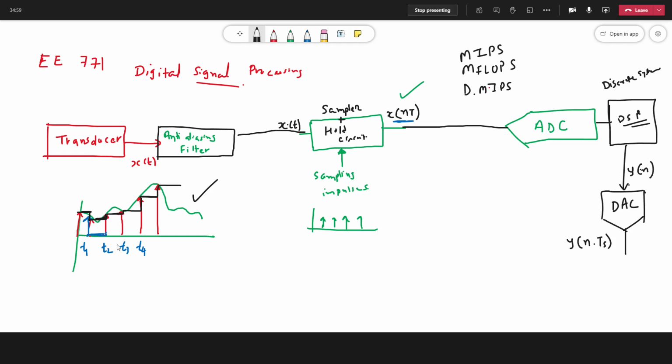So these are the moment when digital to analog converter will change its output suddenly. Now this sudden change in signal actually represents presence of high frequency components at this time moment. And if you play such a music signal on the speaker, the sound quality will be really too bad.